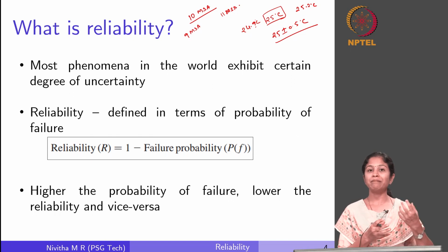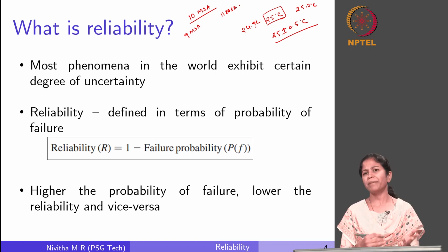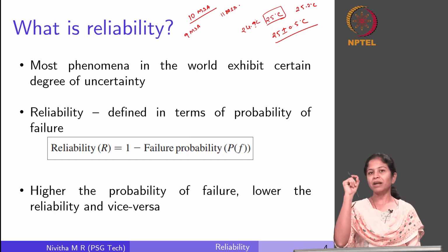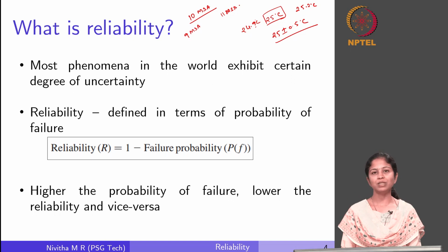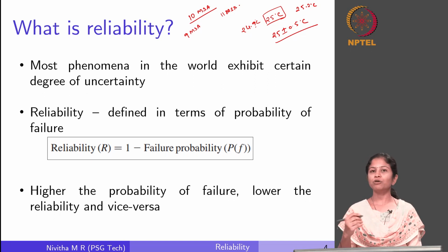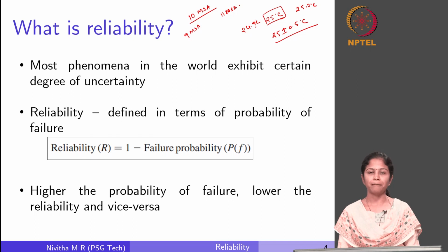We have a lot of input parameters which we use in design. So let us say we have a modulus, we have thickness, Poisson's ratio, then we have traffic parameters, so many input parameters. When we are designing, we give one single point value to all these measurements, right, and based on that I am computing my critical strain values, and for those critical strain values I am computing the number of repetitions to failure. So what if there is some variation in one of those input parameters?